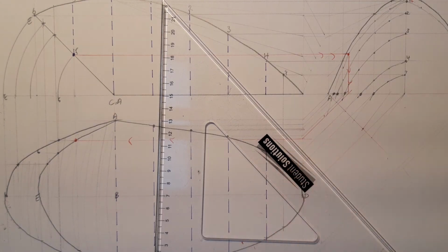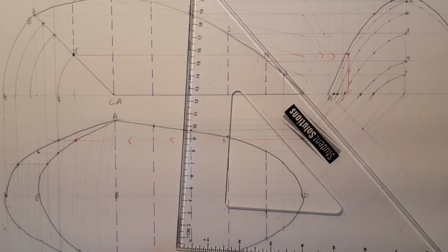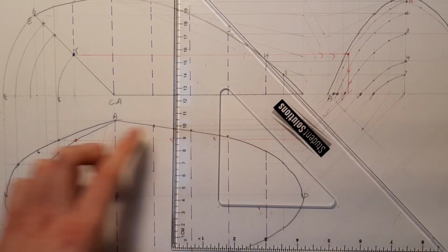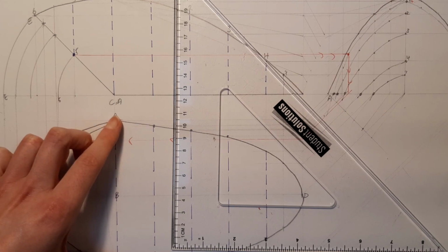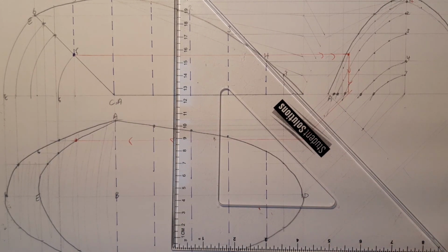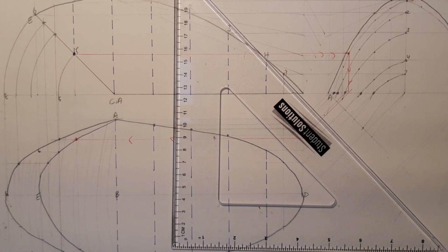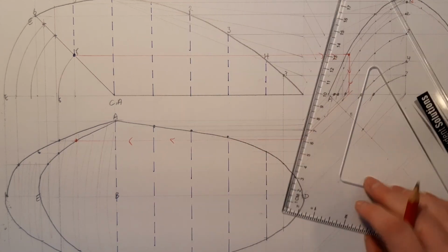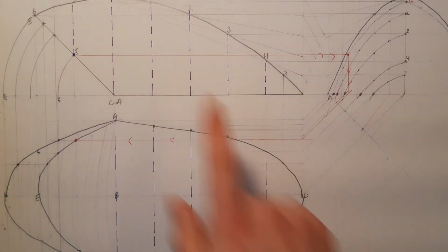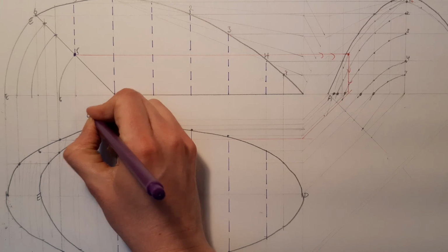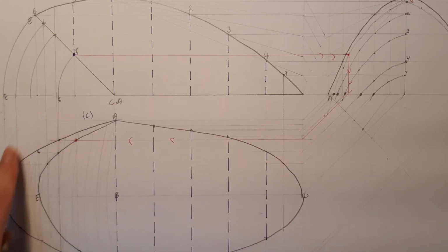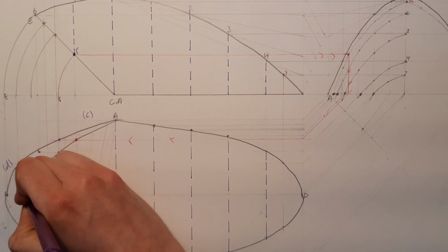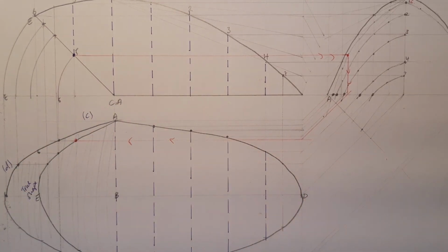If you wanted to, you could have done it out to one side. So what you do is you take this distance on your compass, that would be the height of the parabola. And then you take this distance on your compass, which is the overall width of it, and you transfer it along the base, and you can draw a parabola whatever way you'd like to draw a parabola. And that's the full question done. So I have done, and I just need to label it now, A, B, this part is C, and the true shape underneath here is part D. Okay, and that's the question fully finished.